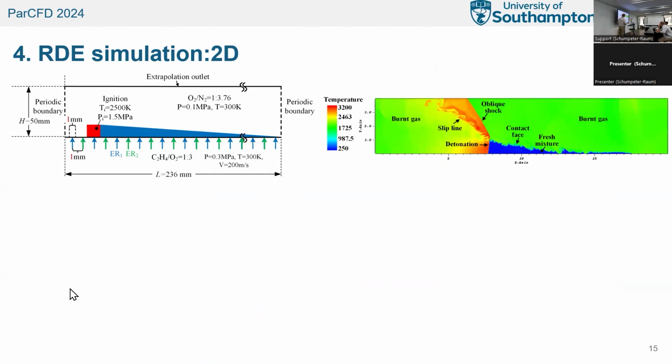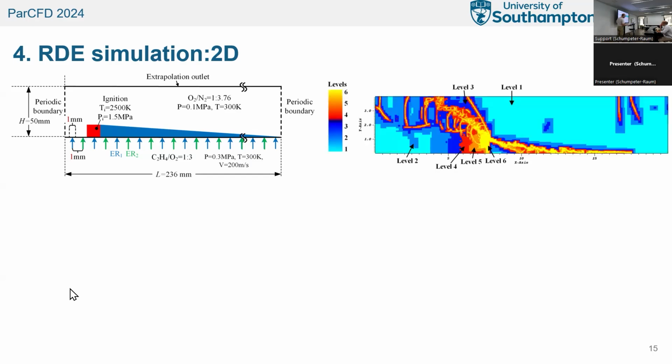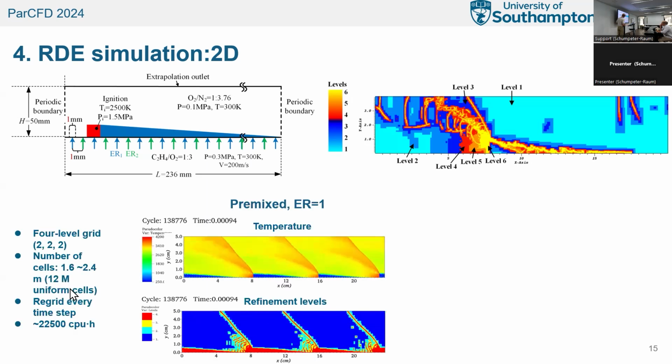So how do we do that? Of course, we don't have a pre-detonator in these computations. So we ignite and initiate the detonation wave with an analytic 1D detonation wave that is painted in the red region. And then this is also common, you inject fuel here triangularly. And that then starts the phenomenon. So here we see some typical physical features. Here the AMR.